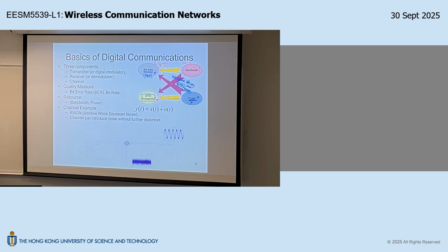When you increase power, you can bring about an increase in bit rate this way. So in order to engage in this direction trade-off, you need to use some specialized modulation family. For example, MPSK. MPSK is one modulation structure that enables you to do this trade-off. By increasing the power, you can achieve higher bit rate, keeping the error probability unchanged.